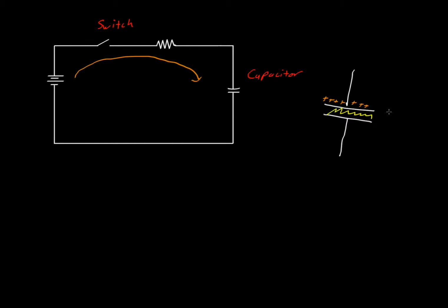And the voltage of the capacitor, based on the fact that it has stored electrostatic potential, is going to go up and push back against your battery. So therefore, you can see that the longer we leave the switch shut, the higher the charge, and eventually the voltage of your capacitor is going to equal the voltage of your source, and current flow will stop.